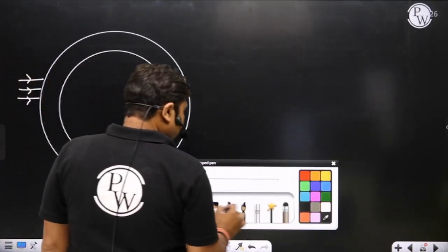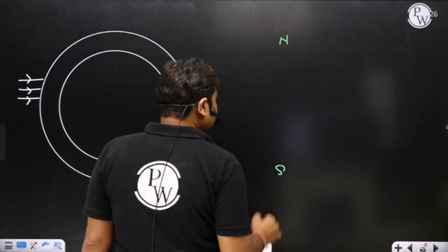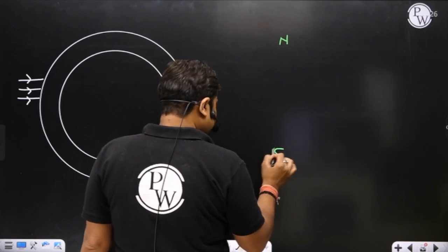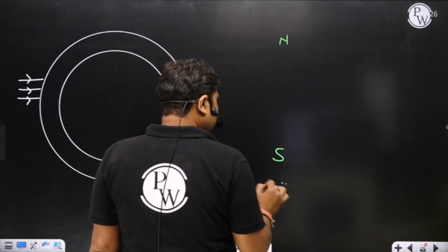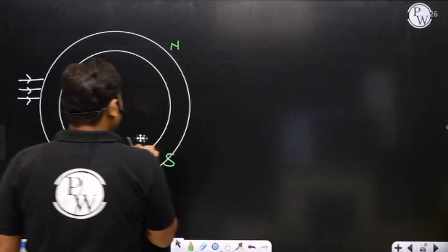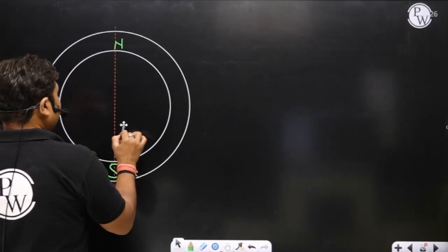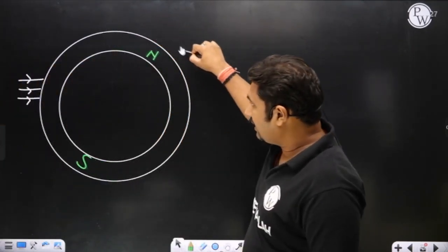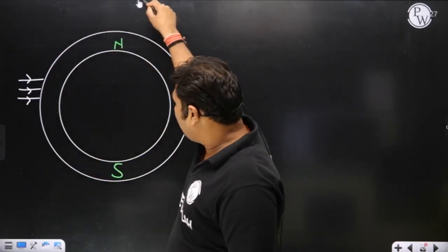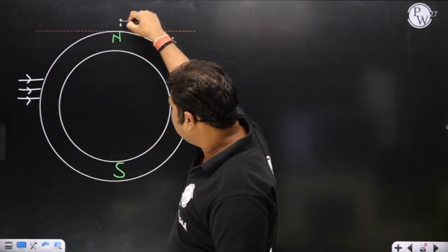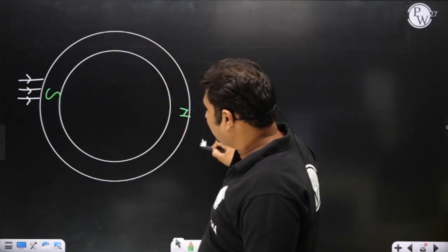So what happens when a 3-phase stator displaced in space by 120 degrees is supplied by 3-phase current displaced in time by 120 degrees? A rotating magnetic field comes into the picture. This is what we call the stator rotating magnetic field, which rotates onto the stator body.